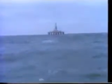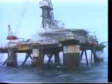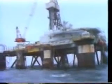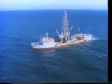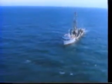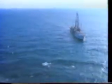Rather than resting on the seafloor, semi-submersible drilling rigs are in a different class of offshore vessels. They float. The drilling deck on a semi is supported by submerged pontoons and kept stationary by anchors or sophisticated computer-controlled propellers. Their ability to float makes these rigs capable of drilling in water depths of several thousand feet. Another type of floater is the drill ship, a self-propelled vessel with a hole through its midsection and a derrick above. A drill ship is capable of storing large amounts of drilling materials and therefore operating for long periods at remote locations.